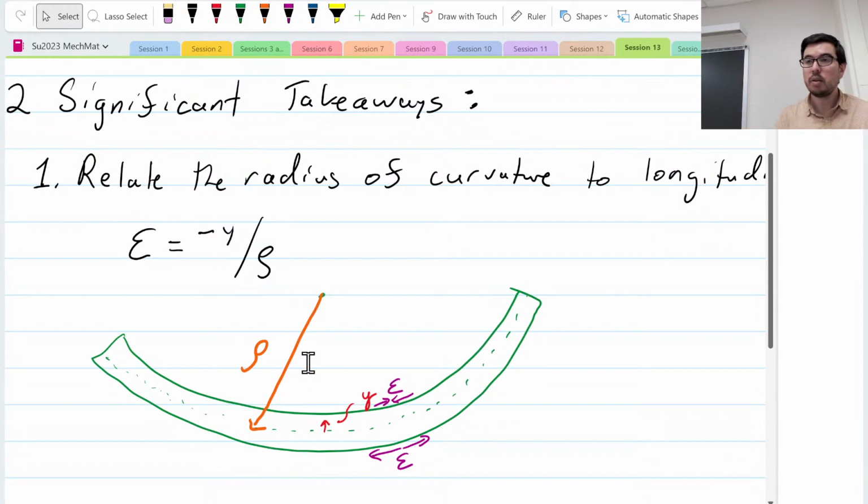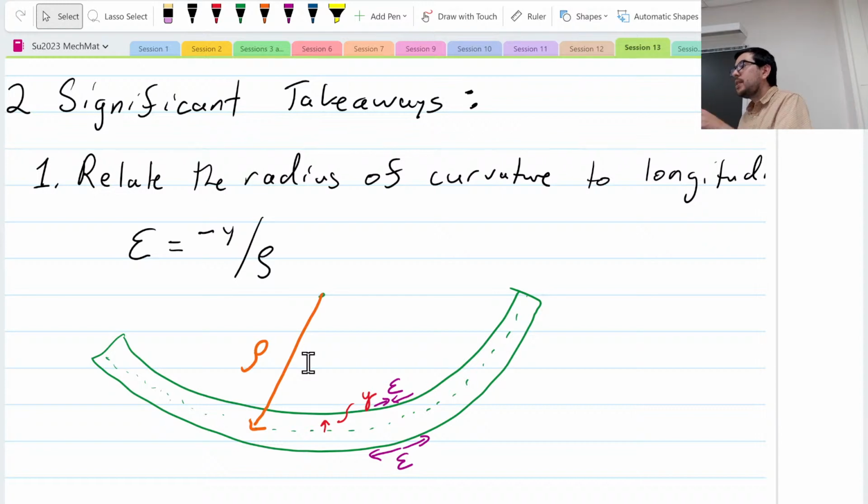Now one more thing, is c just like the radius of the beam? C we consider to be the thickness of the beam, or h, so we have to be careful what we're defining here. C is often used as the radius for torsion problems, and for a beam with a circular cross section you could use c as well. We just have to be careful here. Good questions, Mark.